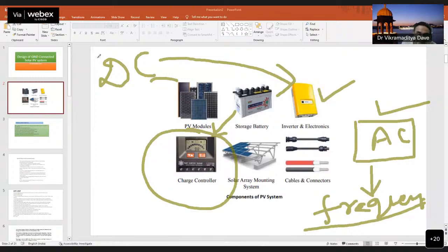तो इन जनरल एक मिसनोमर है कि कोटा से आ रही, कोटा थर्मल पावर स्टेशन से आ रही, मगर ऐसा नहीं है. It is coming from Rawatbhata Atomic Power Plant. 2 units are generating electricity, and they are feeding it to our 220 kV GSS Debari. So this is a very important point. You should know that it is coming at 220 kV Debari, and from Debari it is being given to the different 132 kV substations, like Sukher substation.